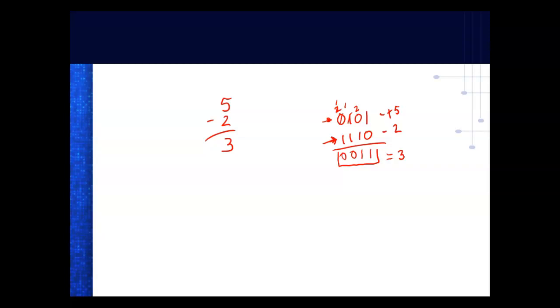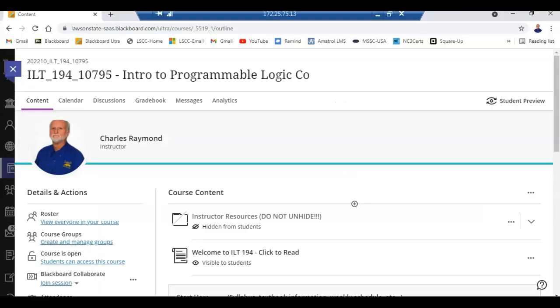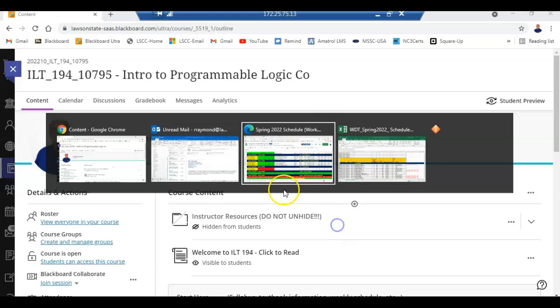So the microprocessor has no addition circuits in it. It has no subtraction circuits in it. What it does, it takes the 2's complement of the bottom number, if I tell it to subtract, and adds the numbers together. Now what happens is it limits the number of positive numbers we can have and negative numbers. So here we're dealing with this slide right here. And we'll tell you why we came up with these numbers. Where you don't understand it, that is okay at this point.